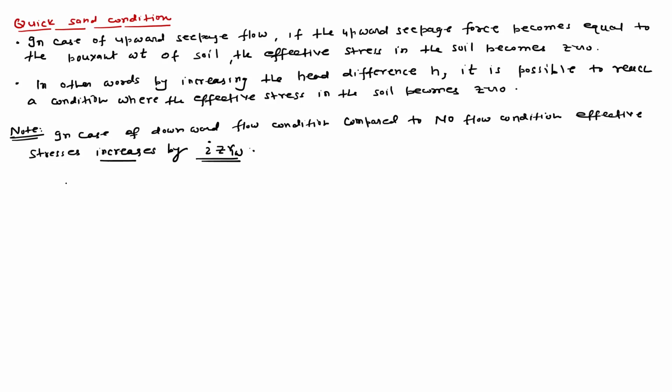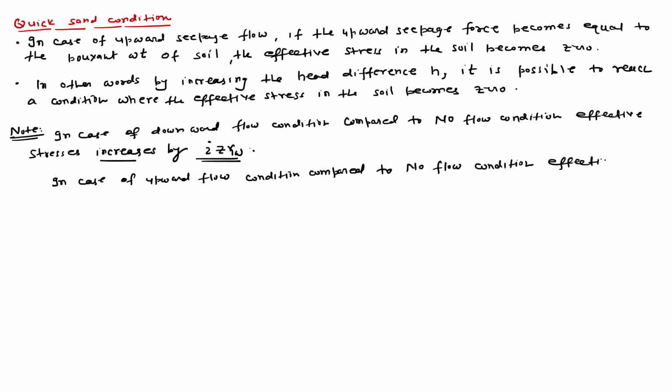But in case of upward flow, compared to no flow condition, effective stress decreases by the same amount, i z gamma w.